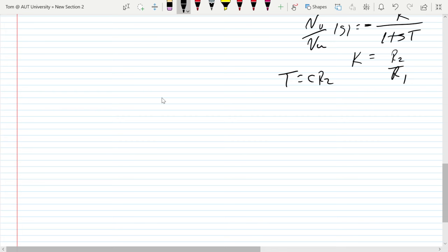That tells us that to digitize something, we have to sample at least twice the bandwidth of the signal we're dealing with, or greater than twice. And usually twice isn't enough. We usually do 3 to 4 times or so to get a little bit more resolution. Sometimes it causes problems even if you follow the sampling rule and don't sample high enough.